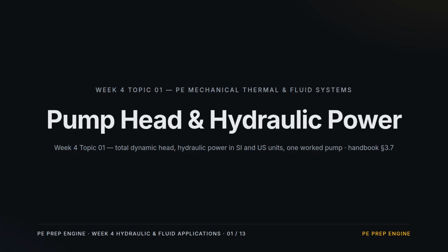Topic 1 of Week 4, Pump Head and Hydraulic Power. We turn pressure, velocity, and elevation into one length called head, the universal currency of every pump problem. Then convert head and flow into power in SI and US units.